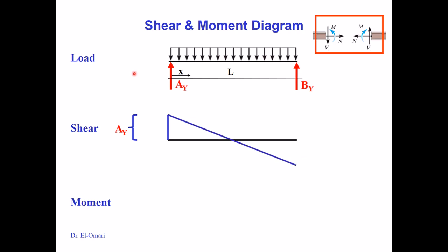If you cut immediately before, notice here that it has to start from zero and end at zero. So the shear starts with the value of the support at the left, going upwards, and it has to end also at zero. So I can actually plot both points and then connect them with the diagram.